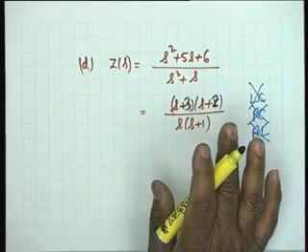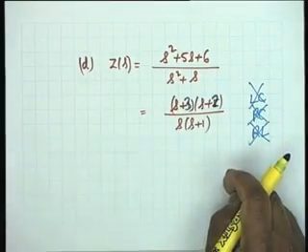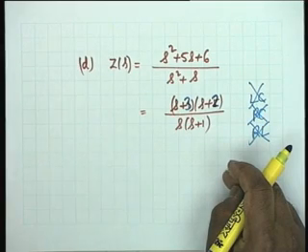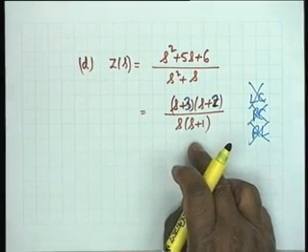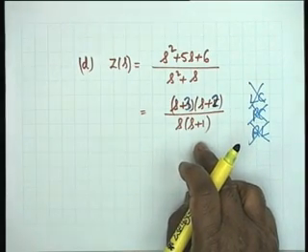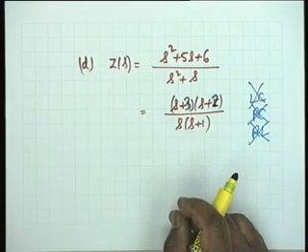Other things are obvious. Yeah, positive realness, but positive realness requires several tests. It requires checking whether the function is real for s real, whether it has j omega axis poles. All other things are obvious, isn't it? It's real for s real. There are no poles on the j omega axis, or there are? There is a pole at s equal to 0. Is the residue real and positive? Yes, the residue is 6. Therefore, it is real and positive. That part is satisfied. What else? Only the real part. That's right.